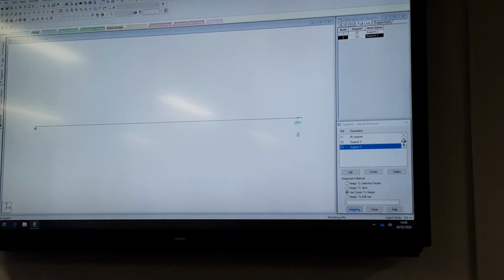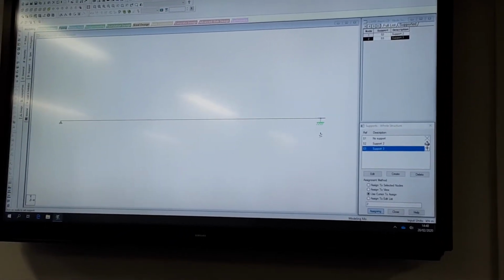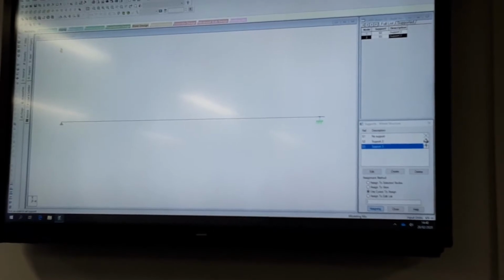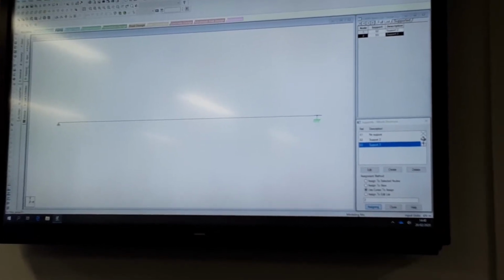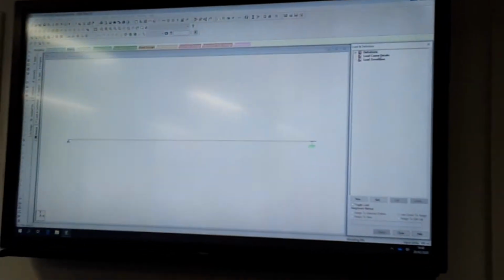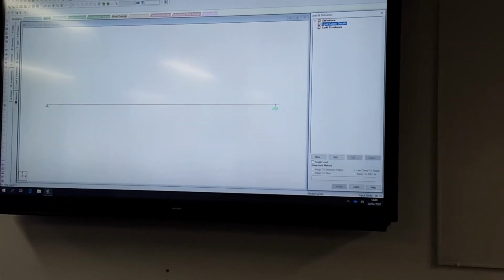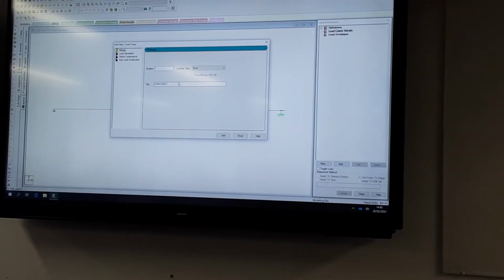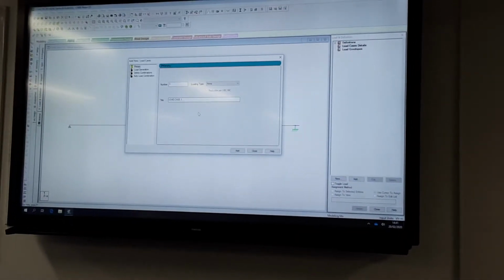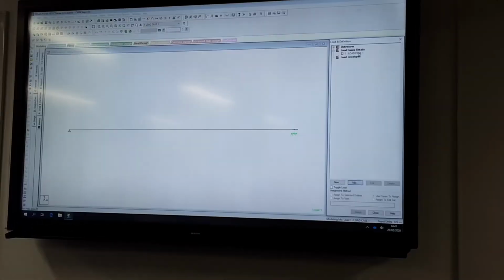The next and the most difficult thing is to define and assign loads. But today it is simpler than the other day. So let's go to load definitions, and let us first of all define a load case. Click on load case, and then click on add, then say load case 1 or any load case, and then click on add. So you get a load case.